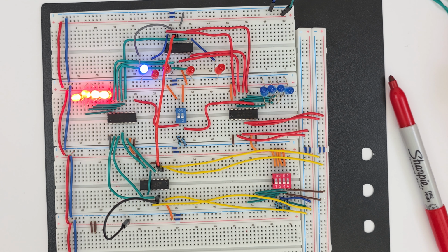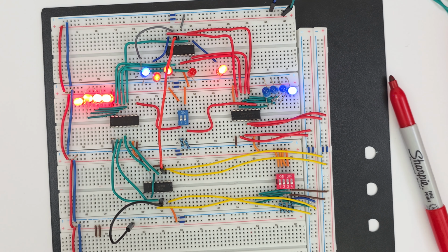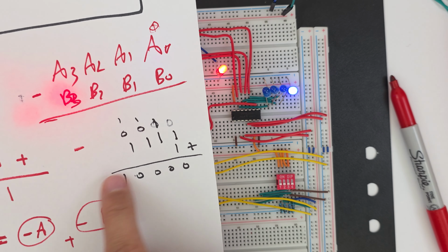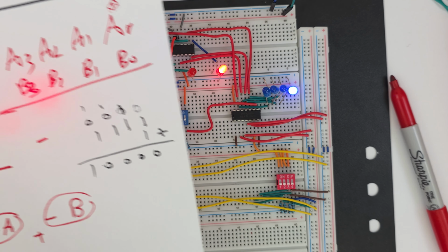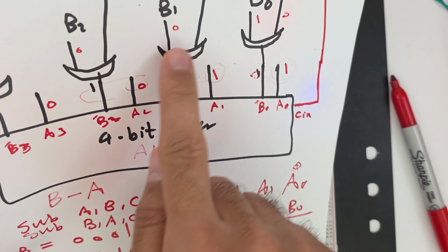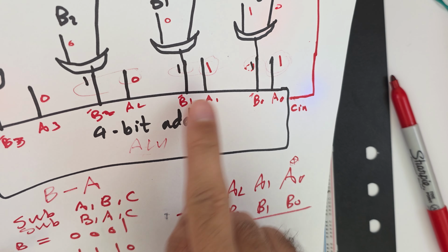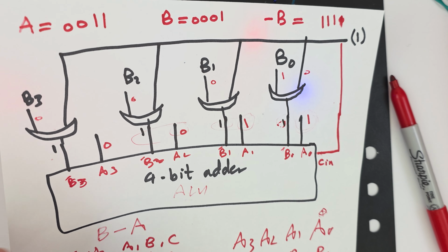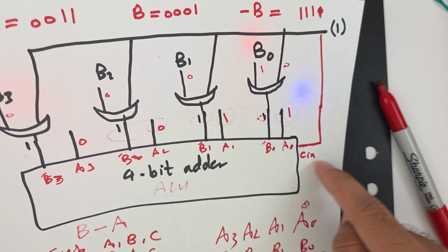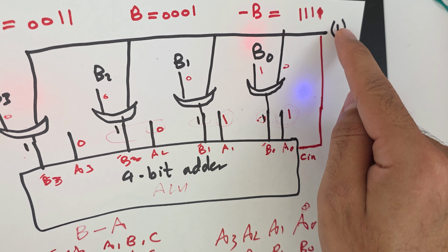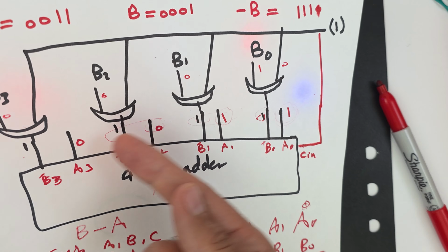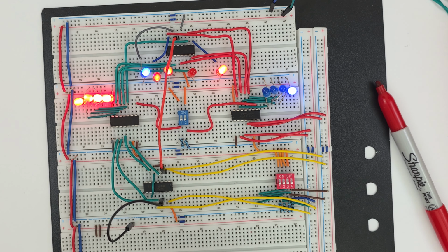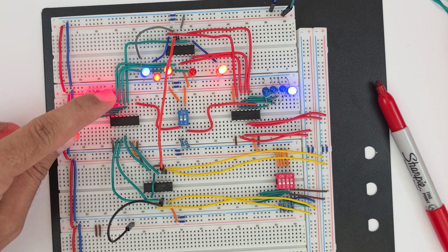This is a question. Yeah, that is expected because the output of the register is not the final value here. It is just this value. If you remember, the output of the gates is not the 2's complement, but it is the negation. It is the first complement. And we add the Cn value equal to 1 in order to take the first complement and convert it to the second complement or the 2's complement. So the output of the register should be the first complement.